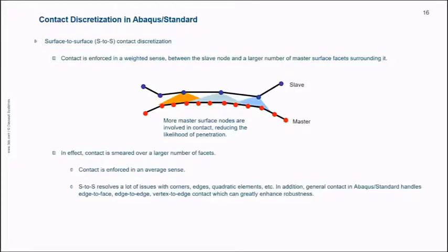All right, so you can see a picture here of what is going on there. The contact is a more involved constraint, and I've heard people refer to a method called the mortar method in reference to this type of surface-to-surface constraint. I don't know exactly what's programmed into Abaqus. Even if I did, I probably wouldn't be allowed to say, because a lot of development cycles went into getting the contact to be the way it is today, and we don't want to give away our tricks, I guess. But suffice it to say that contact is enforced in some sort of average sense.